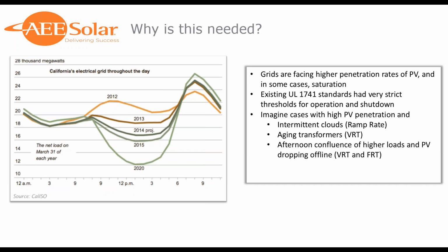Similarly, we've seen systems in the past in Hawaii which had a normal steady state frequency of 57 hertz. So, you'll see in some of the coming slides, 57 hertz is non-qualified in almost every scenario. In those instances, the local utility district passed a sign off where the inverter settings would be adjusted accordingly. So you see that, with increasing PV penetration and these harsh existing standards, you've got the possibility for some really